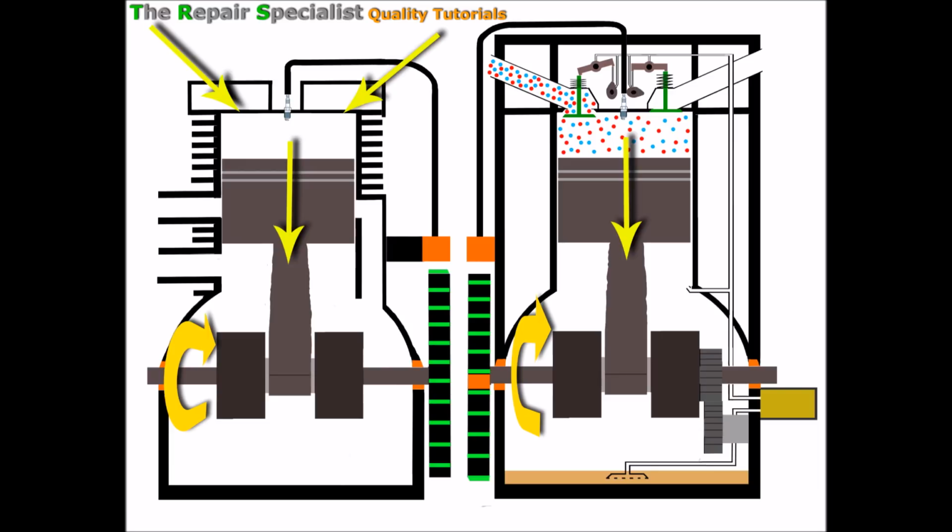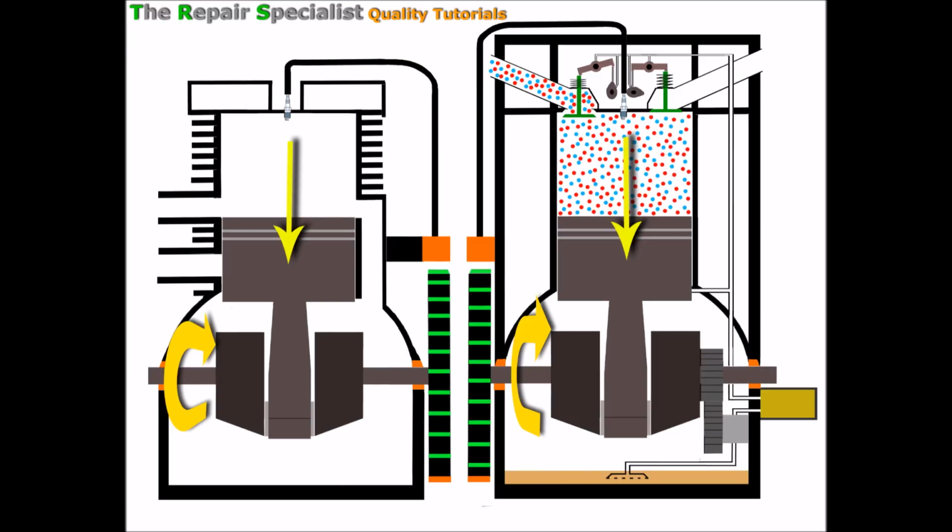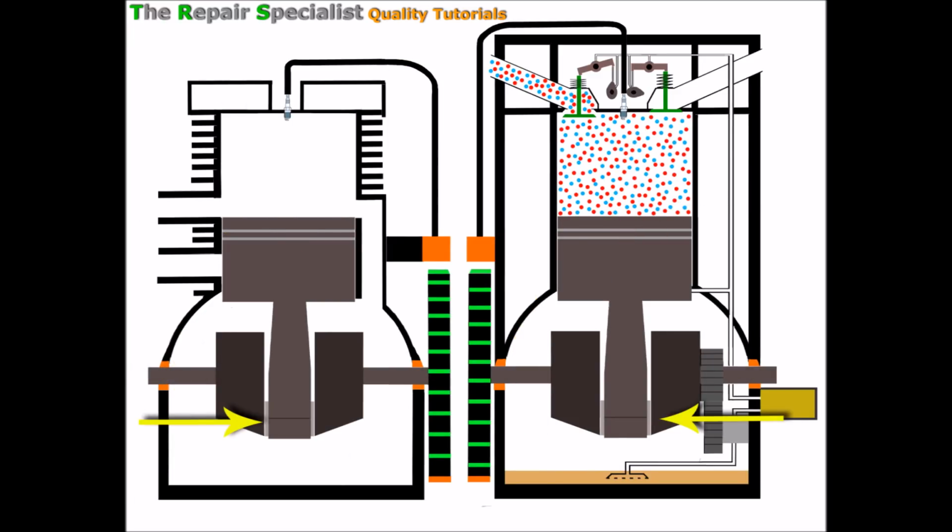And as I've said, at the moment nothing's really happening other than the fact that the piston's lowering. So we're not bringing in any air and fuel yet. Okay, so the pistons have come right down now to the lowermost point, and that's because the crankshafts here at the bottom have gone a full 180 degrees from top dead centre. And so at this point we can clearly see that the 4-stroke engine has continued to bring in that air and fuel on that induction stroke, but now we're at the bottom of the induction stroke, the lowermost point, so we can't draw any more in.